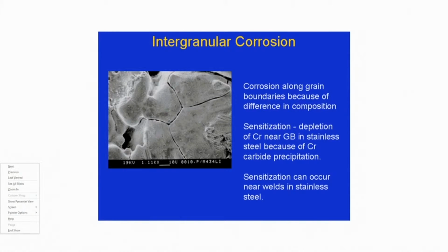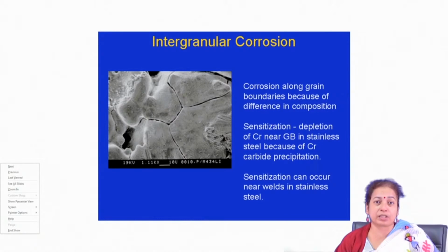So, when we expose the pure metal to a corrosive environment, we find that though the grain boundaries are attacked at a slightly higher rate than the grain bodies, the effect is not so significant. Even if we refine the structure, the corrosion rate of the refined structure is not really so high compared to that of the annealed structure. But if we move in the nanometer direction, we see the corrosion rate of nanostructured materials is, instead of increasing, even lower than that of the annealed, coarse grained microstructure.